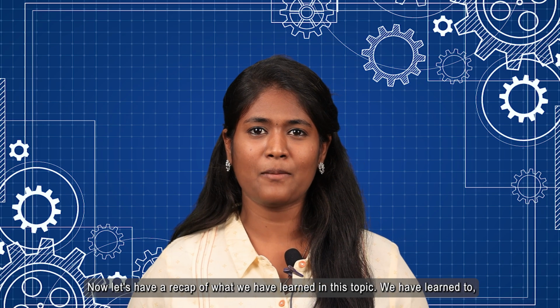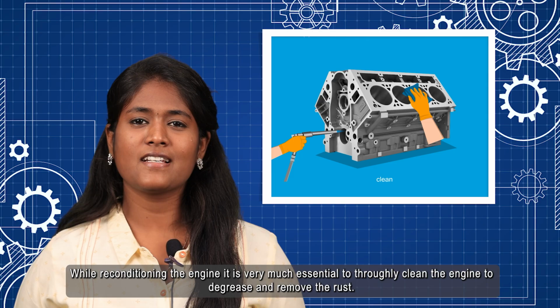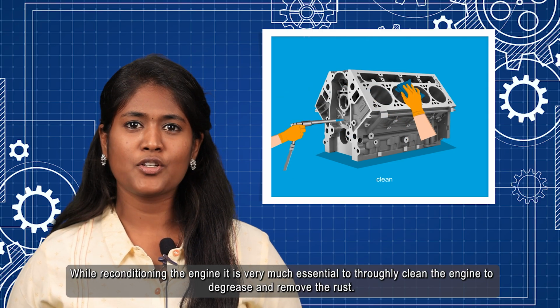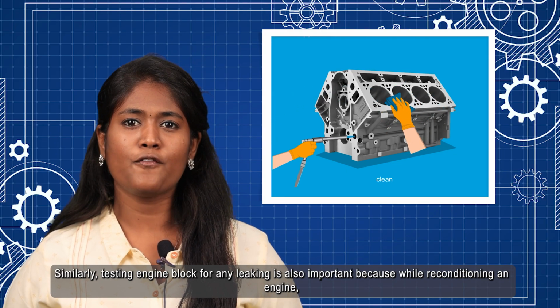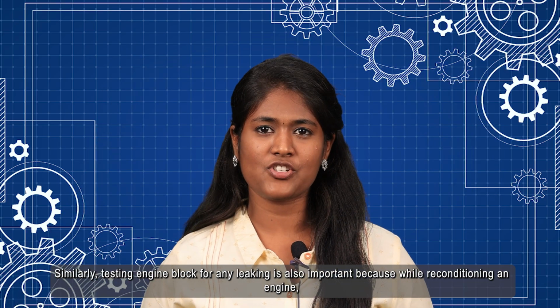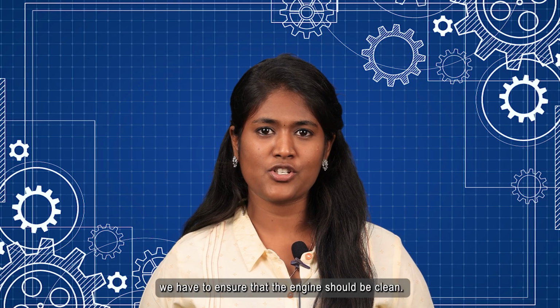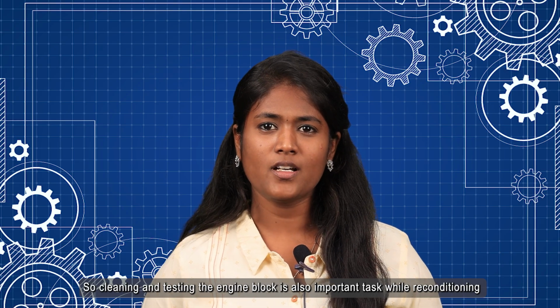Now, let's have a recap of what we learnt in this topic. We have learned to clean the engine block and test the engine block for leaks. While reconditioning the engine, it's very essential to thoroughly clean the engine to remove the rust. Similarly, testing an engine block for any leaking is also important because while reconditioning an engine, we change many parts with new ones. In such cases, we have to ensure that the engine is clean. So cleaning and testing the engine block is an important task while reconditioning.